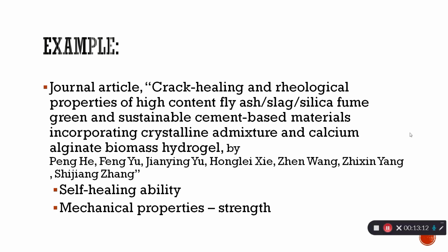Looking at the rheological properties, when fly ash partially replaced cement, the shear stress of fresh paste decreased. There were calcium alginate beads in the paste, and the calcium alginate beads with the fly ash played a bearing role in the shear process, thus reducing it. The hysteresis loop area, which represented destruction of fluid structure caused by shear process with fly ash, decreased. Fly ash significantly reduced the yield stress and plastic viscosity of the paste.